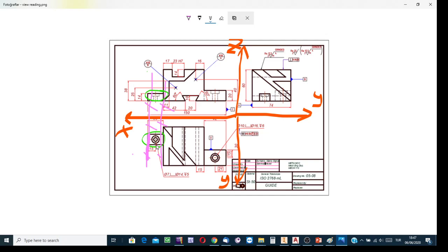I mean, if you know the ABC of orthographic projection and know that the x-axis is commonly used and those are the transfer lines at the view drawing stage, used for having the top view here and the front view there consistent with each other, then you look for the front view of this feature not here, not there. The front view of this cannot be this part of the projection.